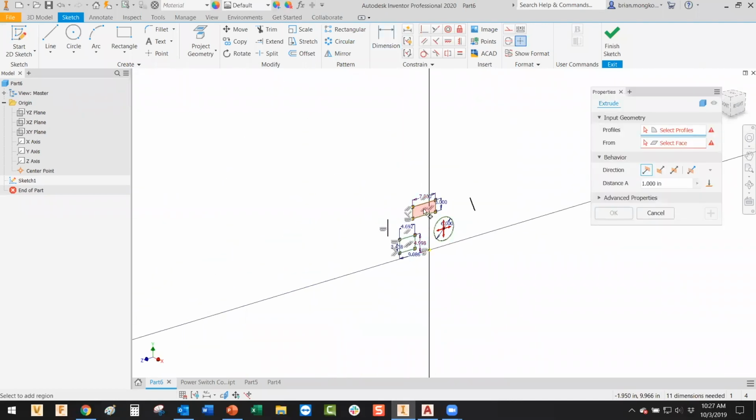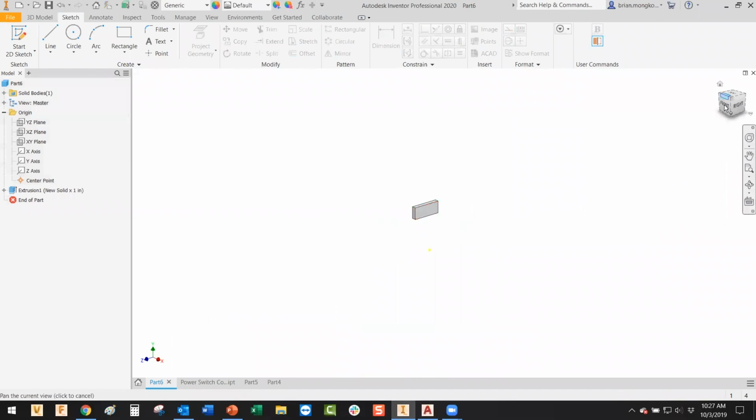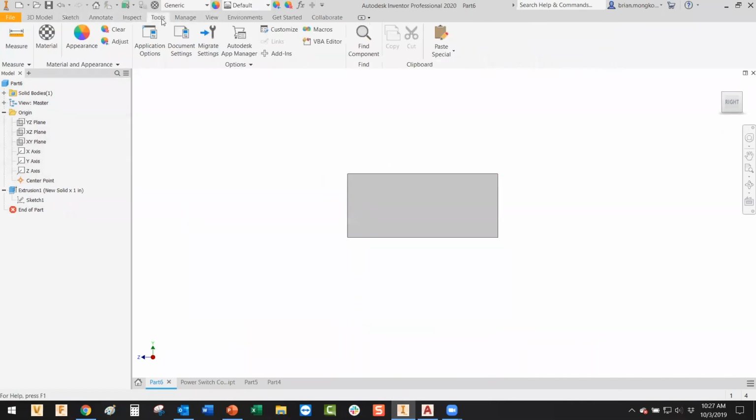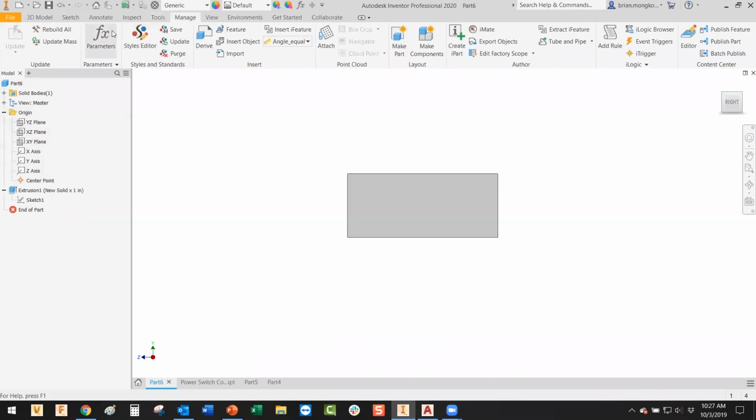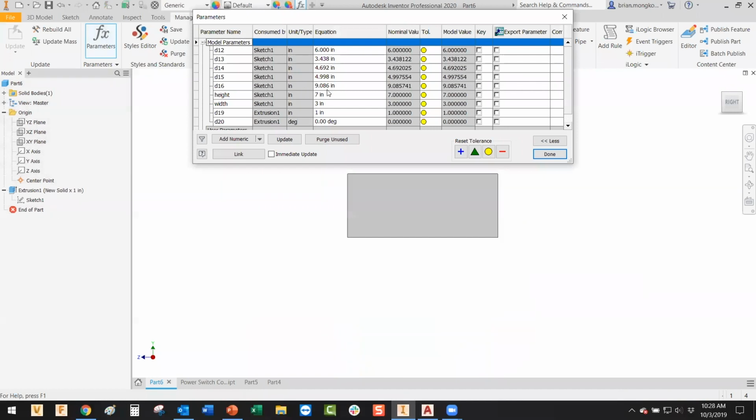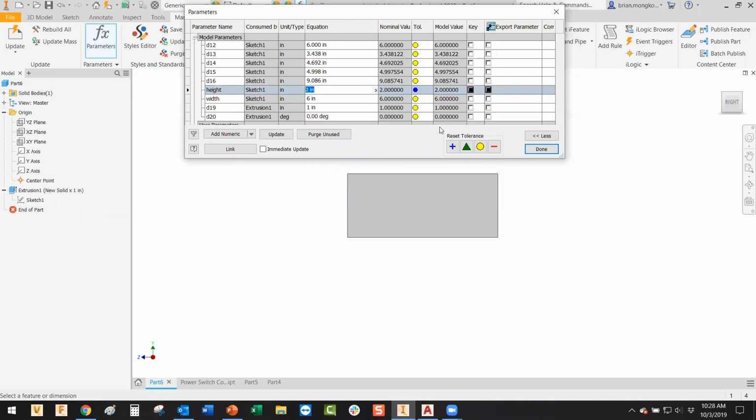And then I go over here to make that a 3D body. Instead of having to dig through my sketches and then going in and changing that value, and if I had more of those 7 inch or 3 inch values that I want to replicate across other parts of my sketch as well, I can just go over here to the parameters window instead and change that newly created parameter without having to go back into my sketch. And this would work for everything in 3D modeling. There's a whole other world of parameters that we can dive into. Just want to point out that this exists.